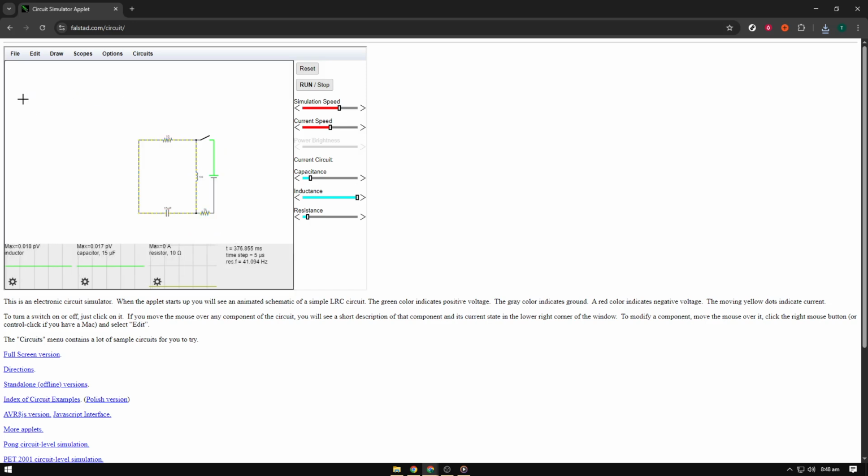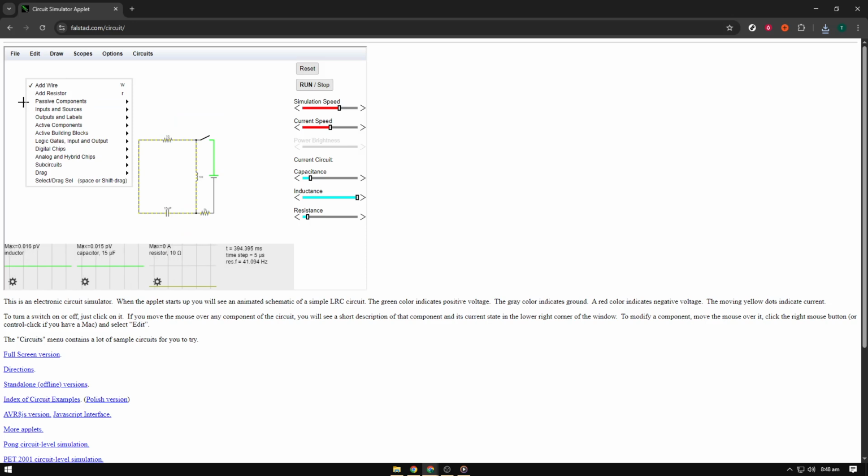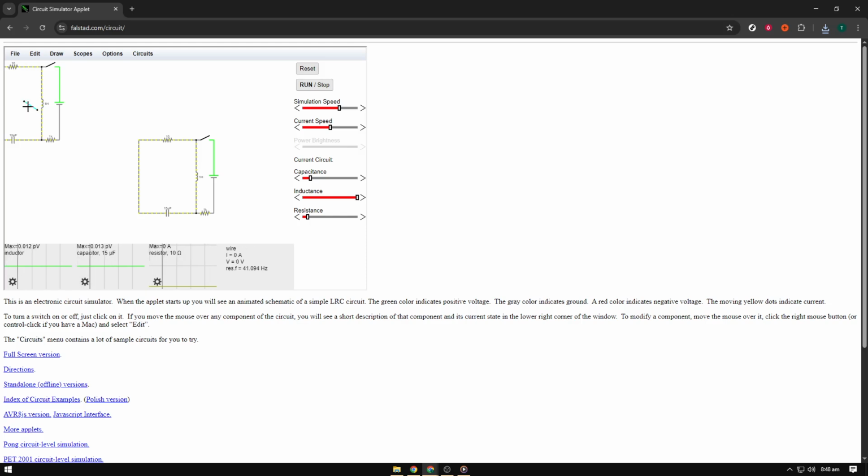Select Paste. The copied circuit elements will appear, maintaining the same spacing and orientation as the original. You can move the group as one unit to position it exactly where you want it. Take advantage of any grid or snapping guides that your workspace provides to align the duplicate cleanly with existing parts. Keep a little breathing room around the placement so you don't accidentally overlap existing nets or components unless that's intentional.